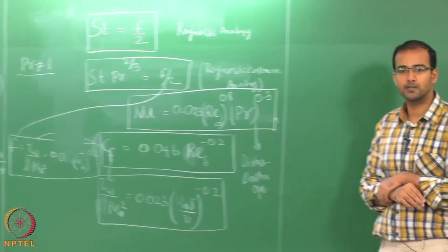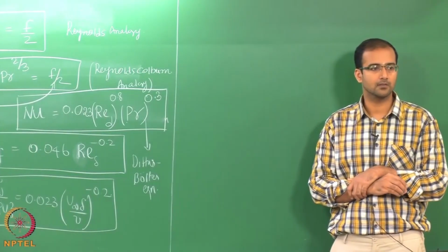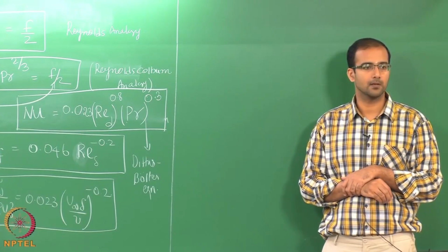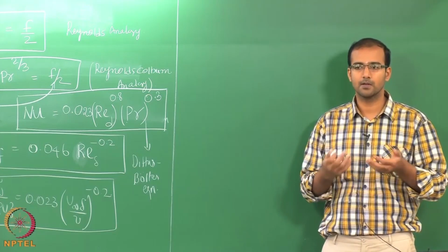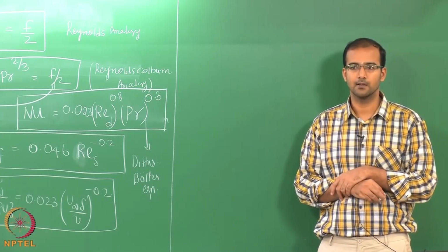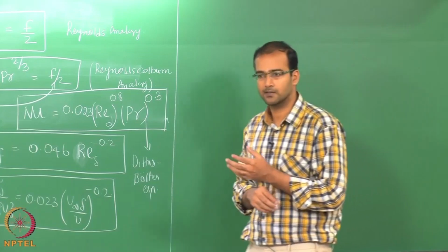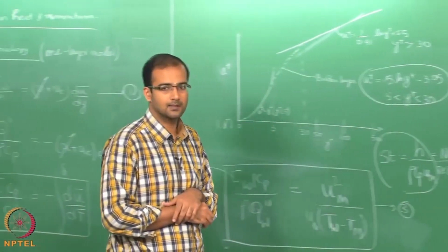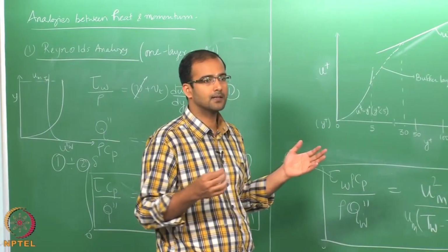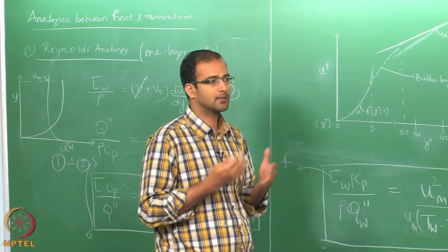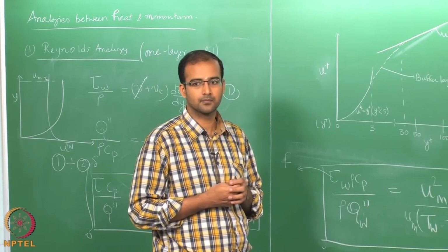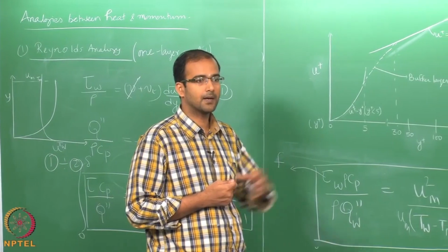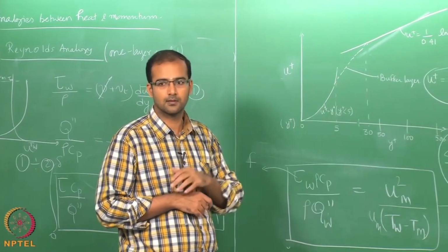It's a very fundamental equation that many people know in turbulent heat transfer in ducts, fully developed turbulent flow through ducts, but you may not know how it is derived. You have used this as a correlation without knowing how it is derived. It is nothing but a simple application of the Reynolds-Colburn analogy. It is not very rigorous, but it has been found to be a reasonably good approximation, within plus or minus 20% of the experiments. When people do experiments on fully developed turbulent pipe flow, they compare with Dittus-Boelter and find that it is very close.